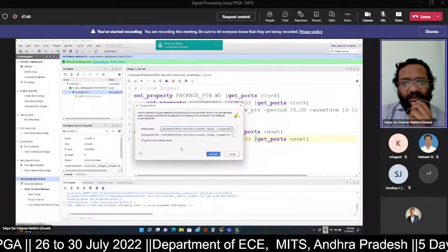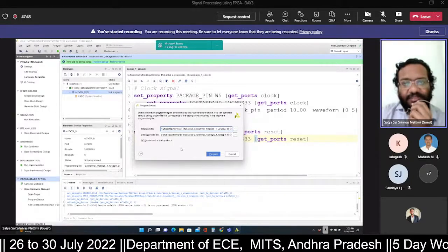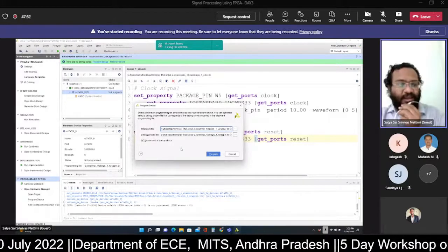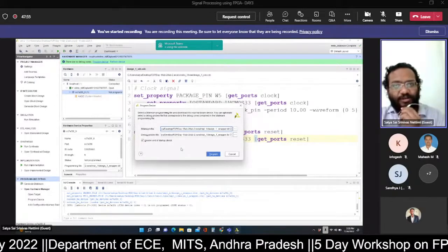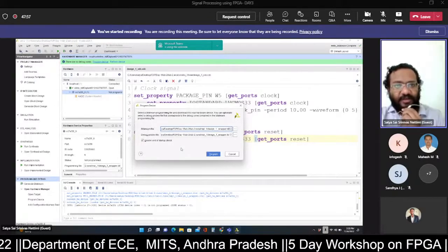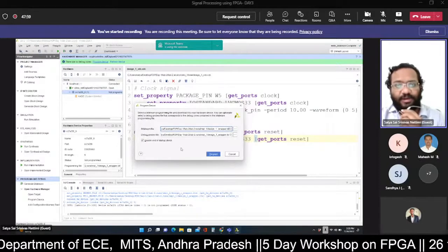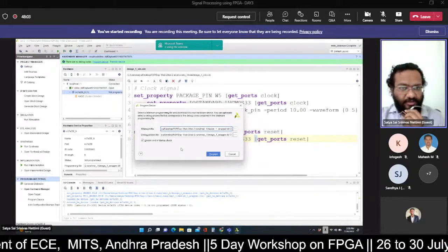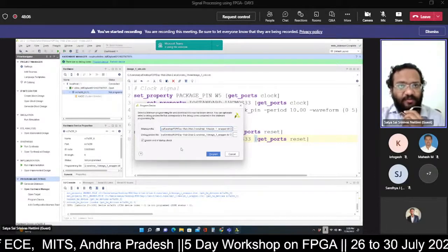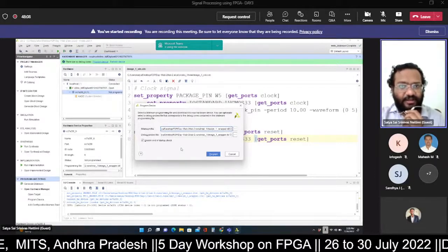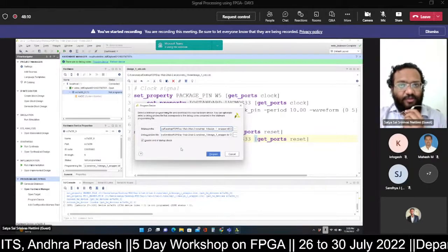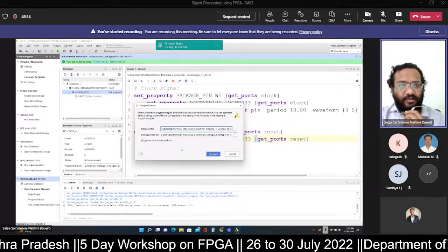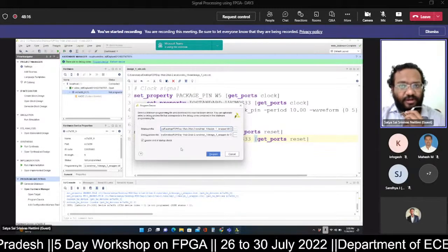And for the hardware, the bitstream file will be generated separately. So these two files will go and sit on the corresponding hardware, released on the FPGA. Then, since we have used this debug IP core, a two-way communication portal will be established and a new terminal window will pop up on your screen. Through that, we can run our hardware and make your circuit run.